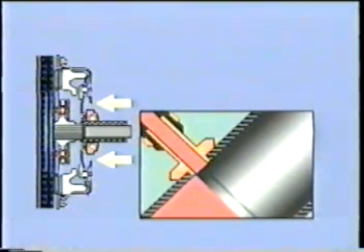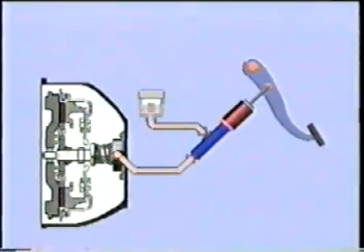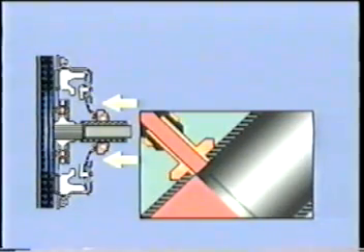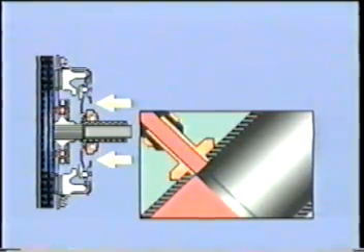If the recuperation orifice becomes blocked, the system will not be able to equalize. Instead of surging back into the reservoir, fluid is trapped inside the pressure chamber. When the vehicle heats up, the fluid expands, forcing the slave cylinder outward, partially actuating the clutch. Anything which prevents the master cylinder diaphragm from recovering to its correct position or prevents the reservoir expansion diaphragm from properly contracting can cause the clutch to partially disengage by itself.